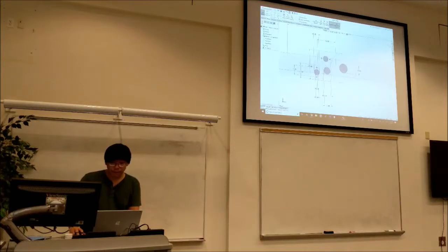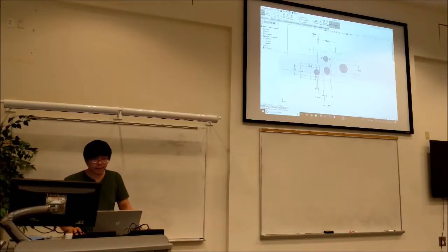So now this is the basic geometry of the gearbox. The rest of it is going to be planning where you're going to put your standoffs, and making sure everything is going to clear each other. Like I said earlier, we're going to put a sprocket here because we're going to drive an elevator or something, or it could be anything, it could be an arm.